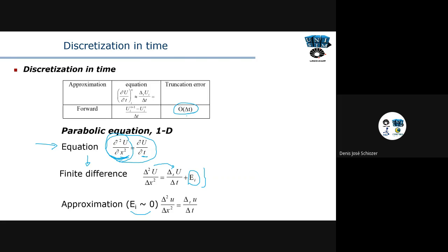But of course, if you have more blocks, we have more equations to solve. It's going to take us more time to solve. And if the time step is smaller, we also solve more times, and we have more time to solve the problem. So again, it's a compromise between what we can do and the time we can save, and this is very important for us. We're going to see some practical applications. And probably you are seeing some of this when we are selecting your models for the project you are doing.